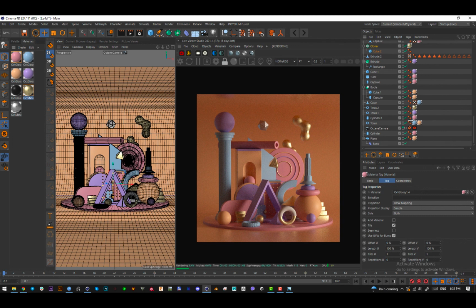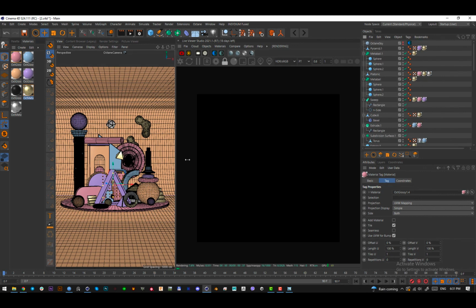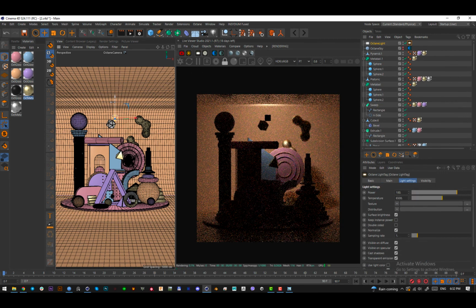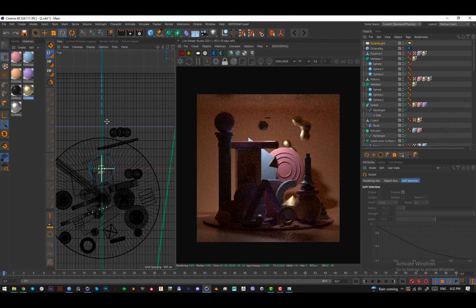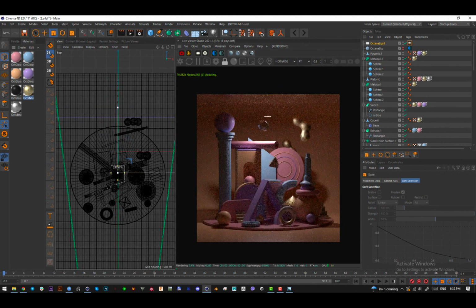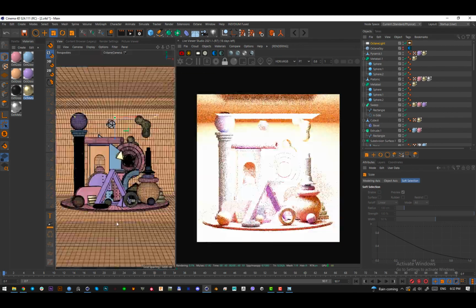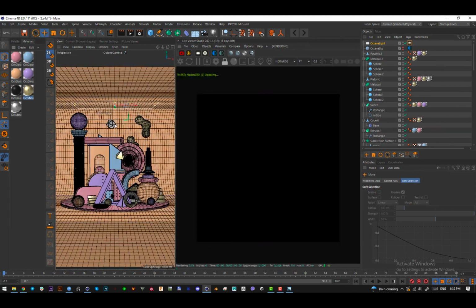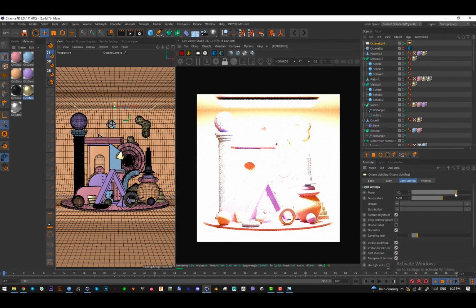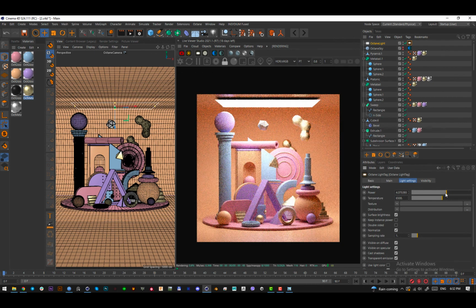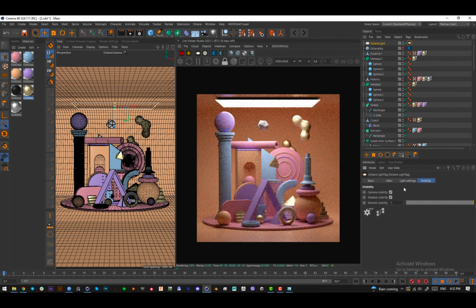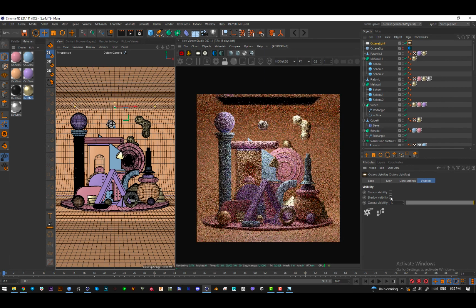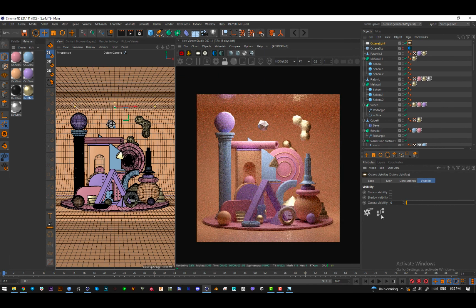Let's turn off our HDRI and just light with lights. I'm going to create a light here and pull it up. Let's just put this light on top to see how it would look. So rotate it like this and increase its width. It's blowing everything out, but put it here. Jump into the light, really decrease its power. Jump into visibility, toggle camera visibility, shadow visibility, and general visibility, pull it down.